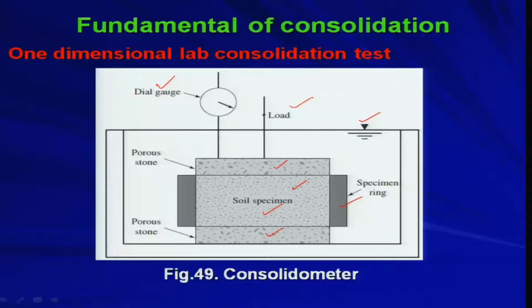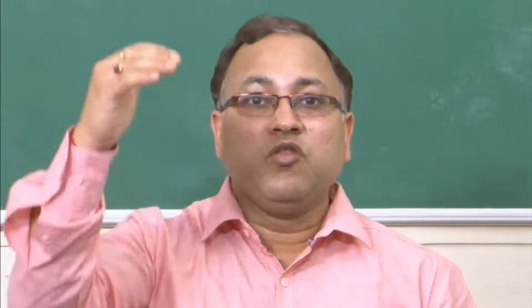Basically we are applying some load on top, and we are observing the height deformation, or the reduction in height, delta H. These two things we are observing, and based on that we will develop the theory, and we can find out what the deformation will be after a certain time, or at different stress increments.